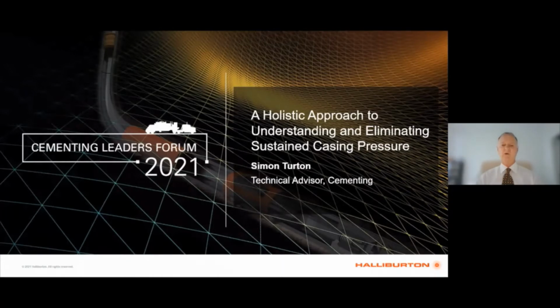This presentation will cover an industry definition of sustained casing pressure, an introduction into published regulations and guidelines, how sustained casing pressure occurs and when, calculations to predict hydrocarbon flow through unset cement, and tailored and technical solutions for successful cement placement across reservoirs that may produce flow.